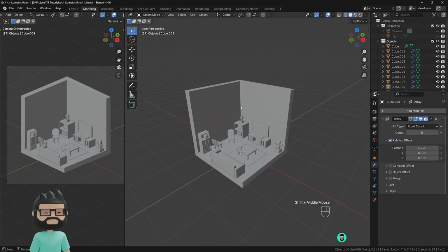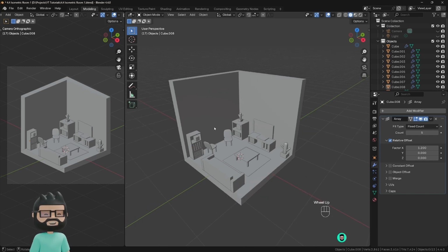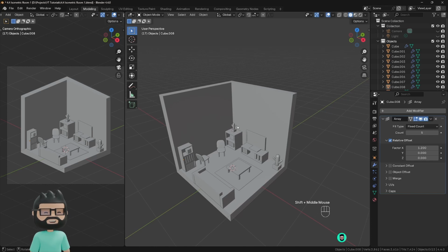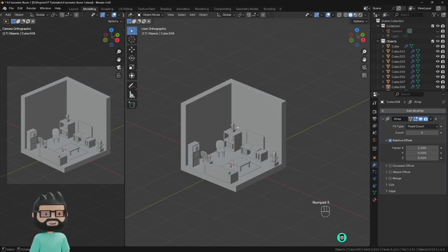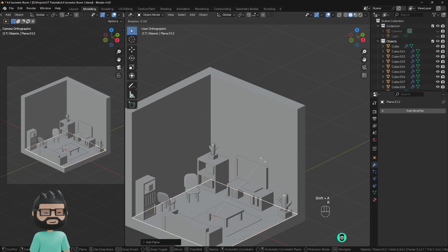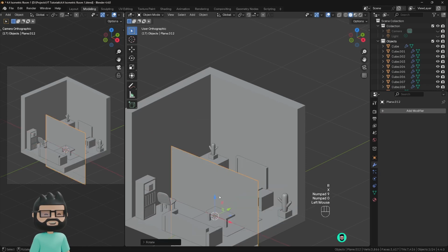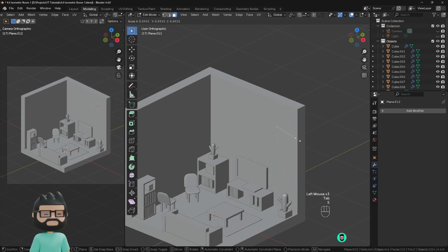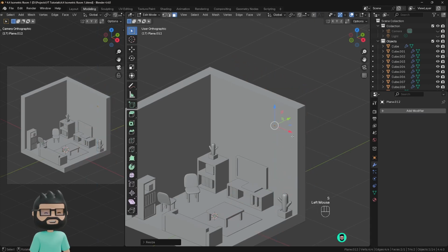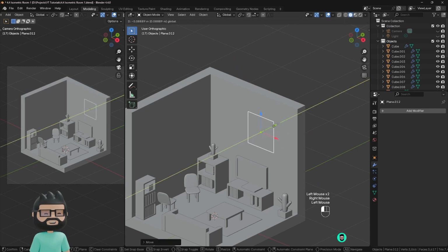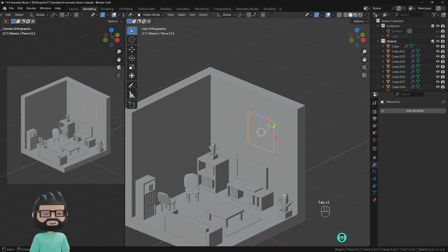Now let's add some image frames to make the room a little more interesting, but basically our room is done. So I'll just speed through this part. So Shift A to add a plane, RX 90 degree to rotate it, move it in the Y, move it in the Z, tab to scale, tab to edit mode, S to scale, move it out till it's visible, tab to go into edit mode, it's still behind.